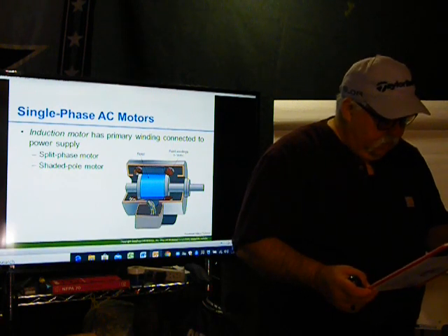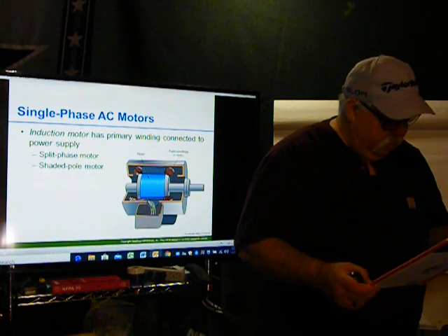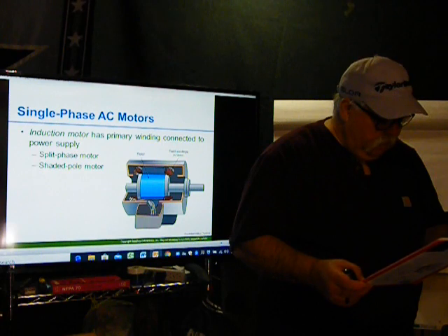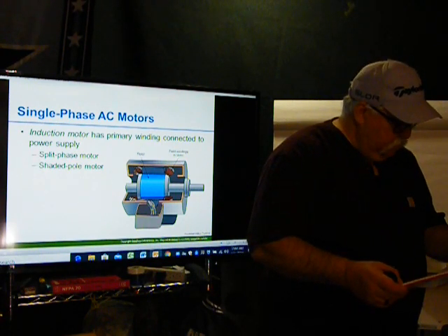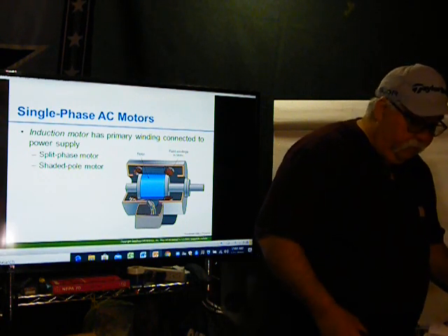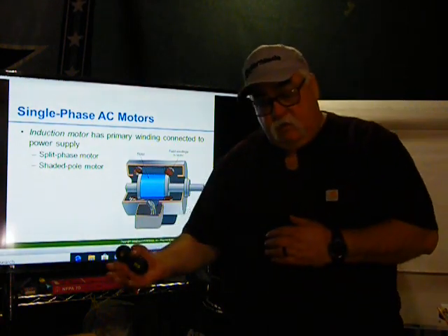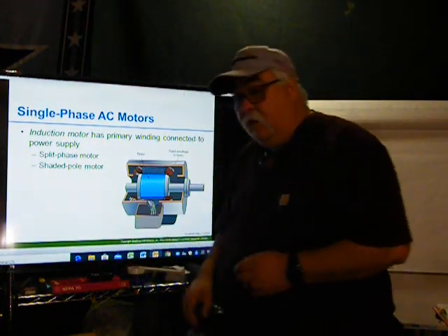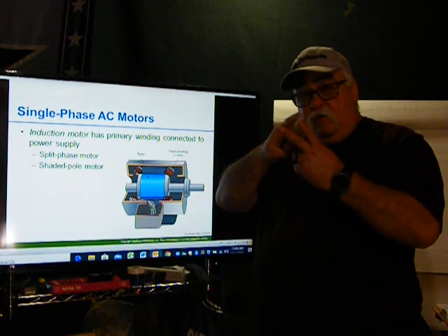There are two classes of AC motors, the single phase and the polyphase. Single phase motors are used in residential and light commercial applications where the service is single phase. The most common type is the polyphase motor, used with three-phase current. Three-phase motors are more efficient and can handle larger loads than single-phase motors. So always remember the difference between a single-phase and a three-phase. When you have a single-phase, say 120 volts, whatever's on the hot, that's it.